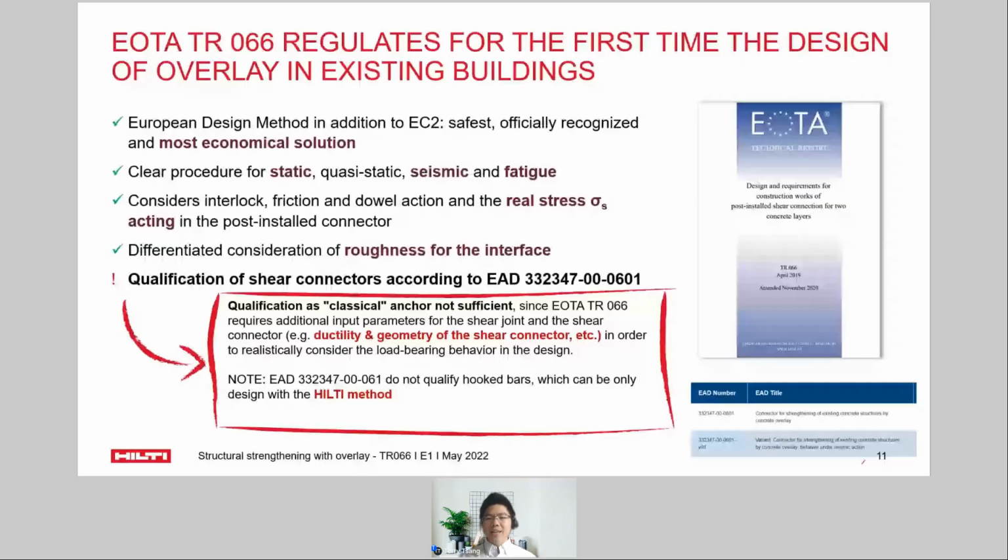So a product carrying such a European Technical Assessment, ETA, or the product approval for standard anchors or standard post-installed rebar, is not fit for concrete overlay unless it has been assessed in this very specific EAD 332347. Then it is fit for concrete overlay use, and it can also be designed according to this technical report TR66.